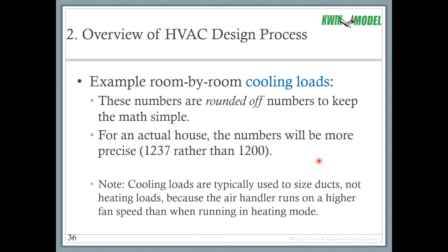Note that cooling load calcs are typically used to size ducts, not heating loads. And the reason is because the air handler in cooling mode will run on a higher fan speed than in heating mode. For example, a typical furnace might have 4 speed taps. There'll be high speed, medium high speed, medium low, and low speed.